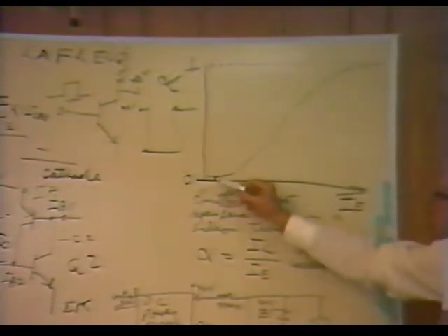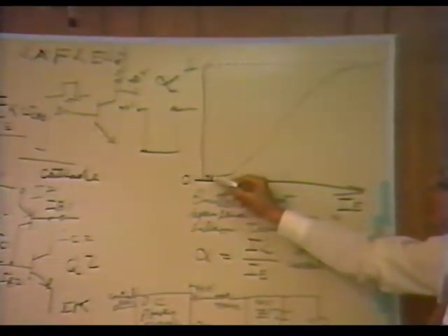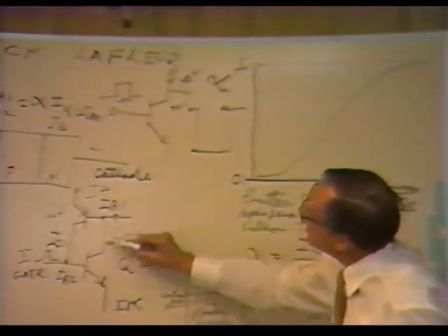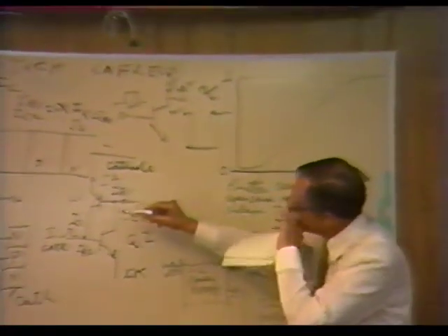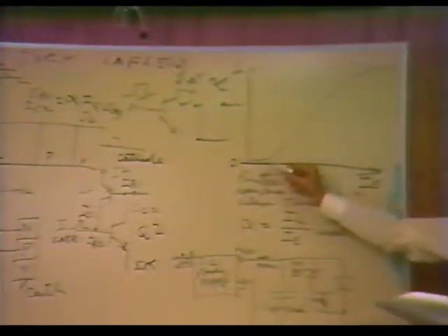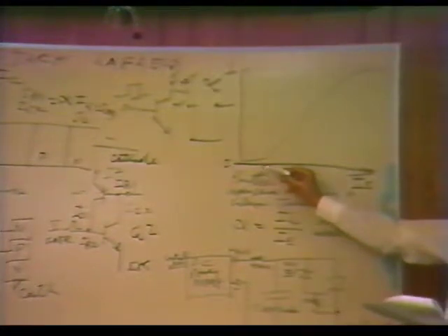Now, why I wanted to tell you that is when these devices are in the blocking state, when the SCR is blocking and these transistors are not on, we have extremely low alphas, and it will block the device because the gate currents or any feedback here is almost all leakage current, and the alphas are so low that they do not turn on.